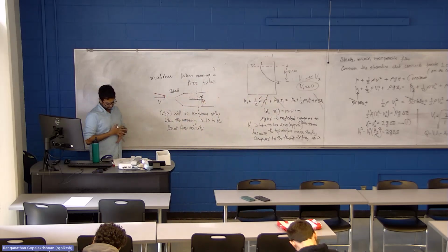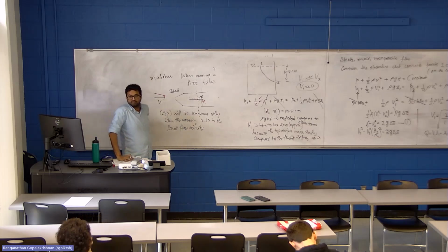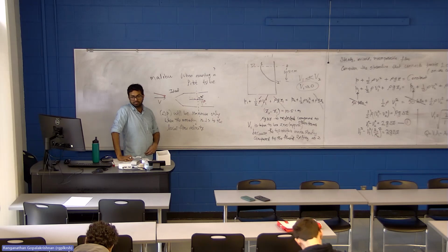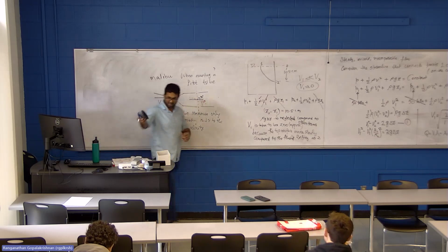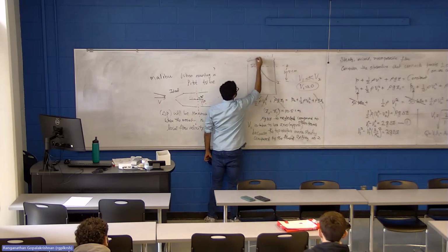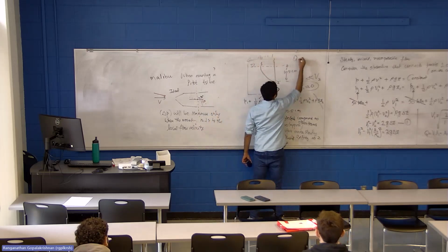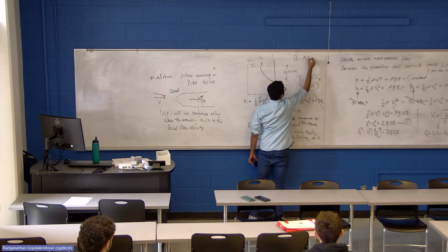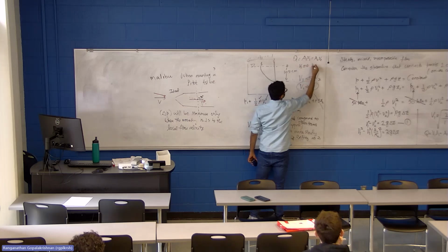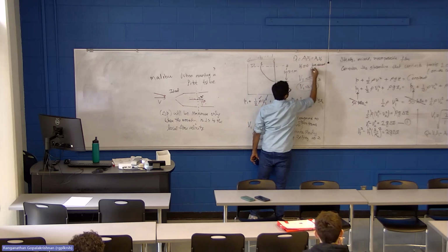If we were to write this another way, like the flow rate and the area and velocity, if we just show the difference in areas, would that work? Brilliant, yes, that's correct. So what he's saying is, if you consider this to be an area A1, and you know that Q is equal to A1 V1 equal to A2 V2, then V1 is small because A2 over A1 is small.